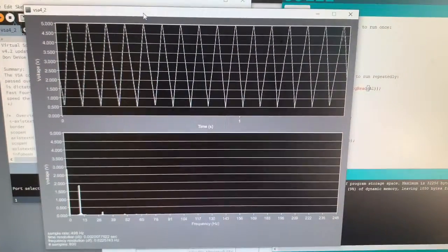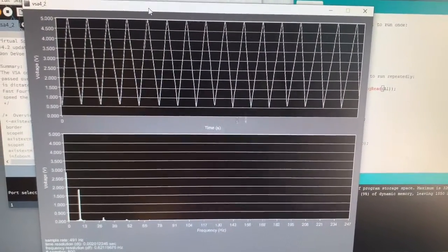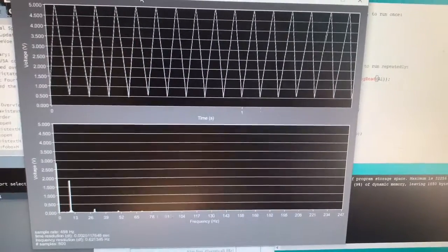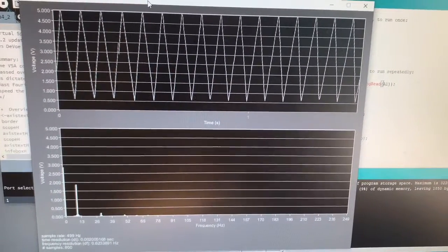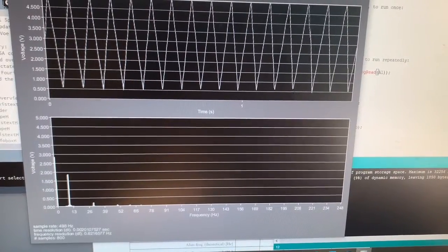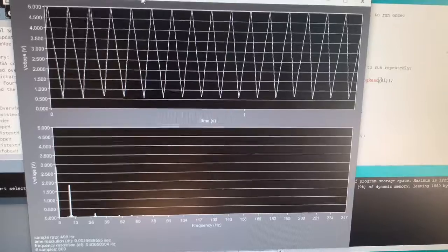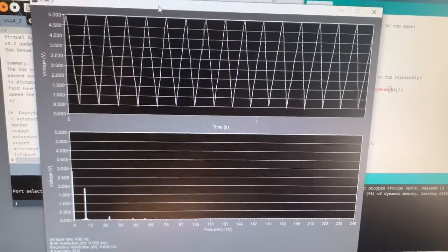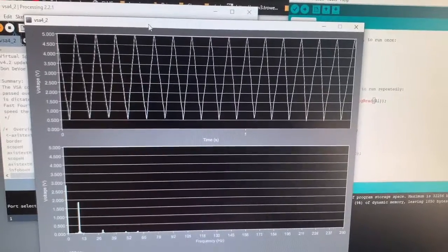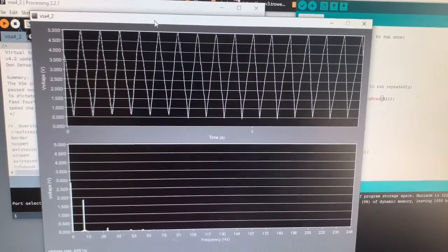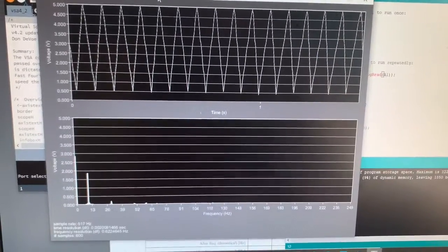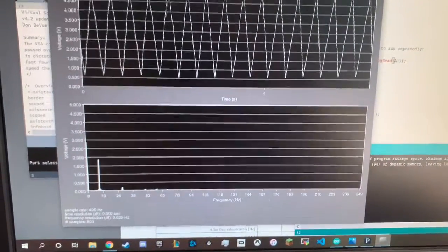And this is interesting because it's getting peaks at 0, 10, 30, 50, it looks like. Slowly decreasing peaks every 20 hertz following 10 hertz. I believe this is because the frequency is set at 10 hertz and the Nyquist frequency for this signal, or the Nyquist rate, would be at every 20 hertz following that.